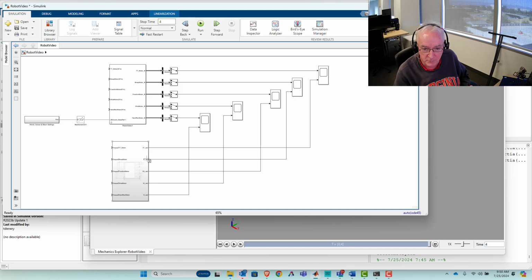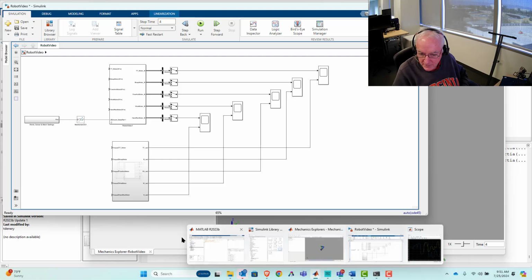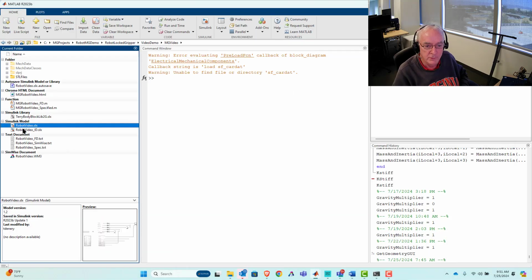Ultimately, what this block and what Simscape Multibody is doing for you is formulating the relationship between the forces and torques applied on a system and the motion that you get. So in this first validation, we showed that for the forces that we're giving, which were mostly gravity, at least for the first 2 seconds, we got a pretty accurate simulation, right? An important reason for doing this too is that we're going to take what we're doing here and do it in the controller too.